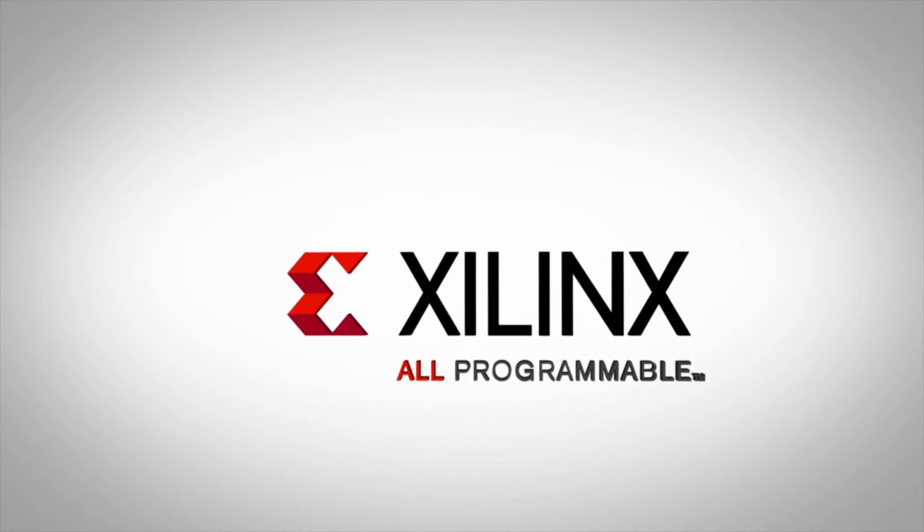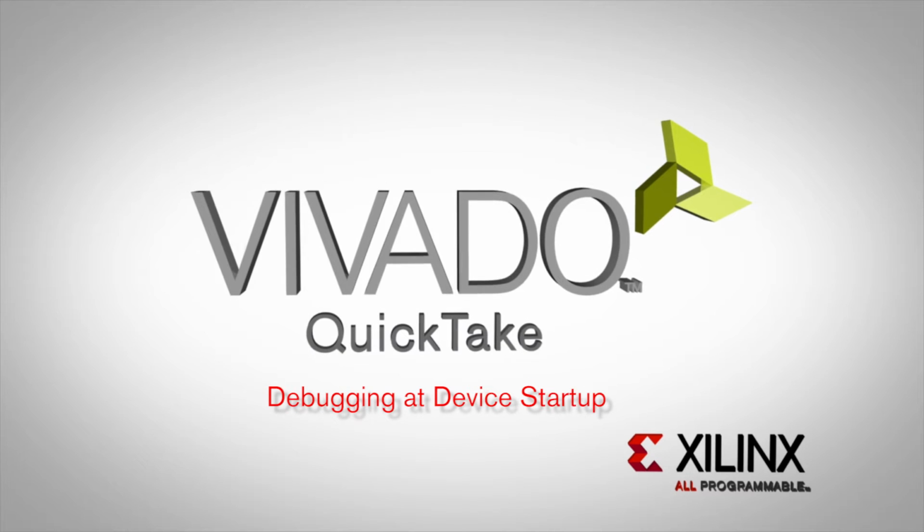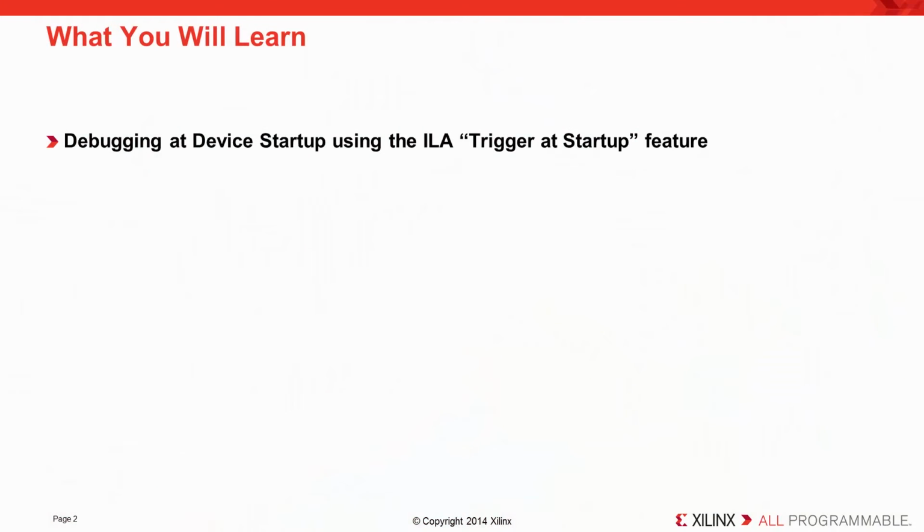Hello and welcome to this Vivado Quick Take video where you will learn about using Vivado to debug at and around device startup. When a design is programmed into a device, there is a device startup sequence that occurs after the bitstream loading phase. You might be interested in debugging around events that occur at the startup phase. It is often too late to trigger around events in the startup sequence as part of your default debug setup.